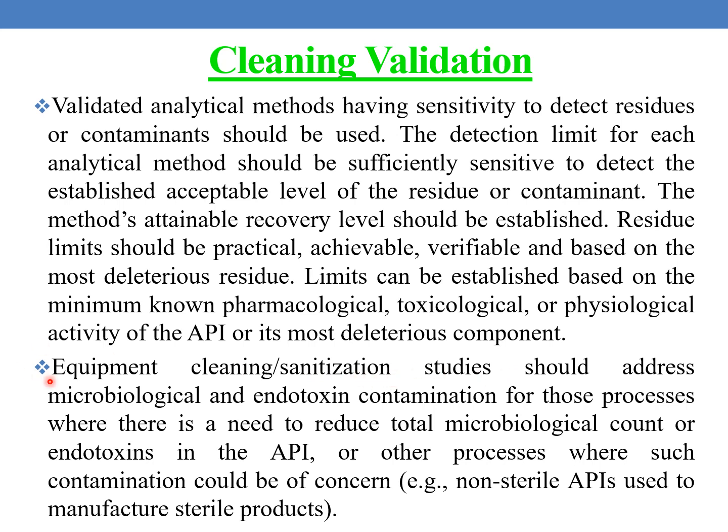Equipment cleaning or sanitization studies should address microbial and endotoxin contamination for those processes where there is a need to reduce the total microbial count or endotoxins in the API, or other processes where such contamination could be a concern. For example, non-sterile APIs used for the manufacturing of sterile products. If non-sterile APIs are used for the manufacturing of sterile products, in such cases the equipment cleaning or sanitization study should address the microbial and endotoxin contamination also.